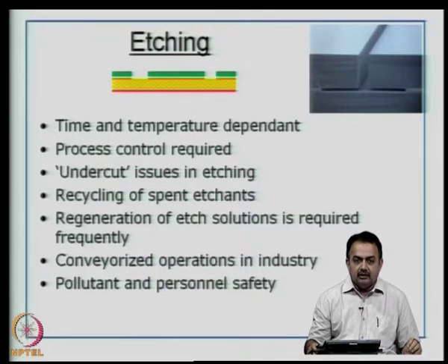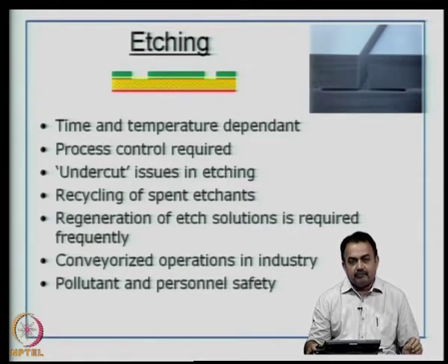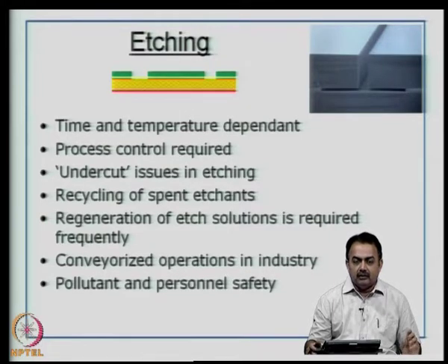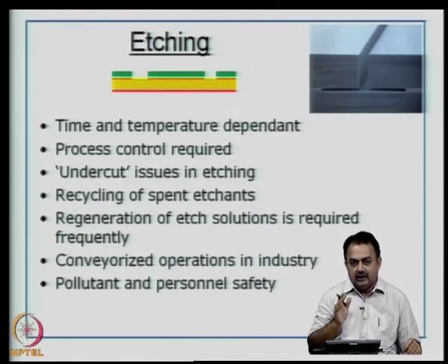Maintenance is a crucial issue if you want to get very high performance etching, and especially if you are doing fine lines, of the order of 4 mils and so on, your etching process has to be well controlled, because time and temperature are going to be closely monitored if you want to etch away a few microns of copper perfectly with very clean edges.